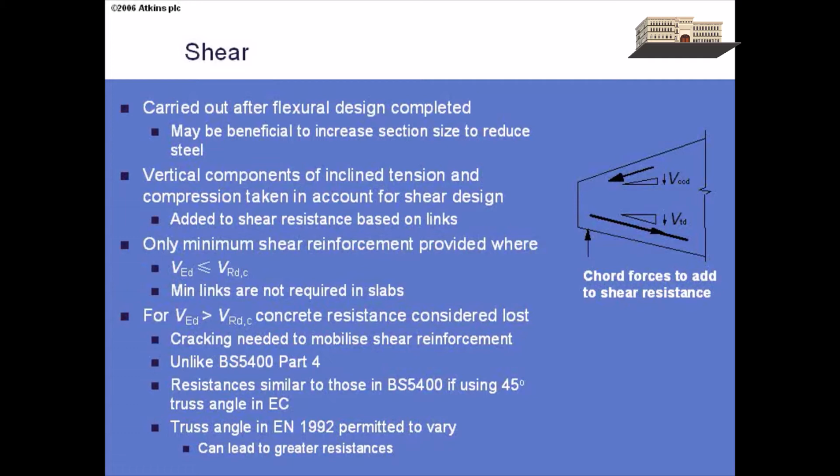So you'll find that the shear resistances require you to know the flexural lever arm, z, because that's a measure of the depth that you've got available for shear, and for sections without links, it will also assume that you already know what the flexural reinforcement is. You'll need that for calculating the shear reinforcement, but also for calculating shear resistance of the concrete. So there's no essential difference in the way we go about shear design. It's exactly the same, but there are a few slight differences.